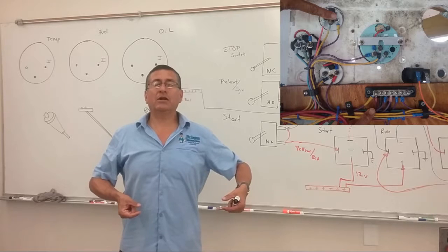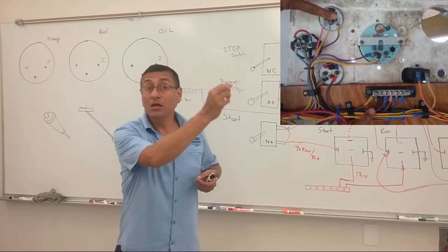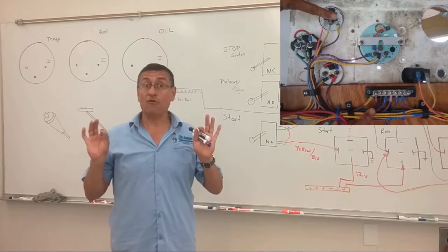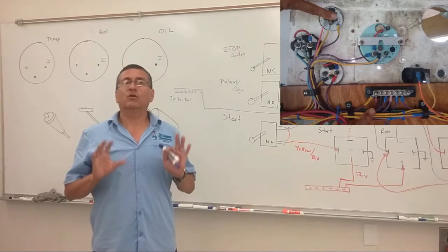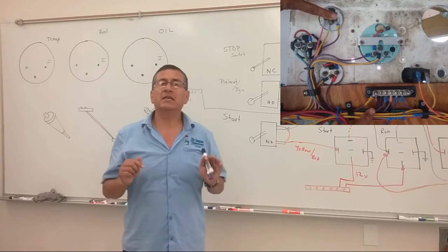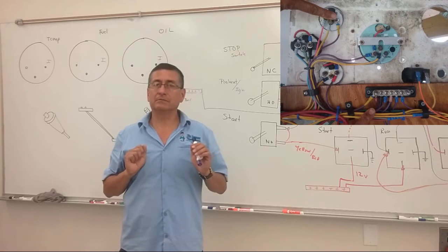And the negative bus bar in the engine room is connected to the bonding conductor, and the bonding with the sink. Don't forget, this is important. Connect the negatives of all the different groups together. If not, after that, it's impossible to send signals.